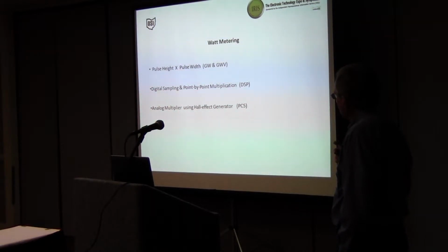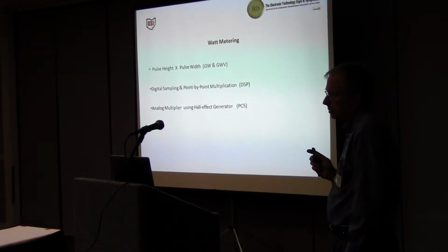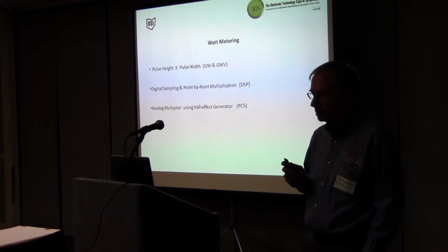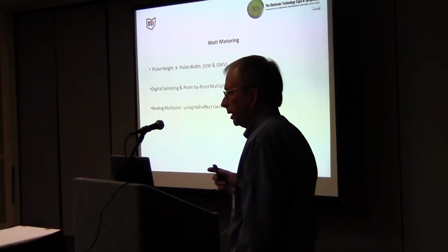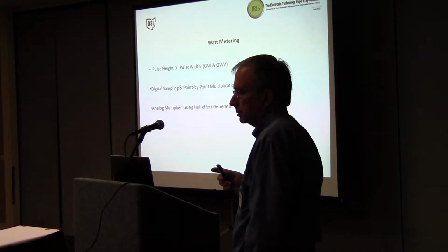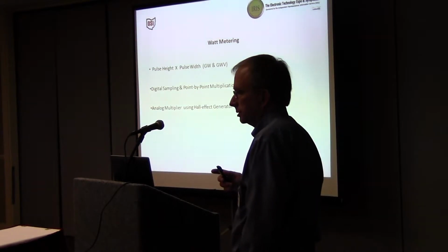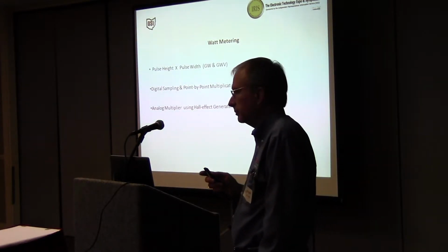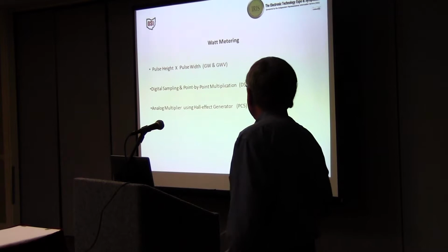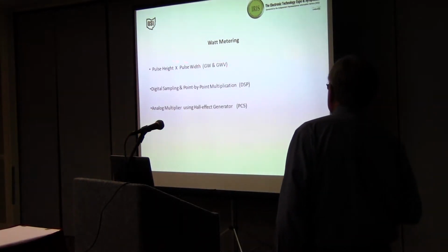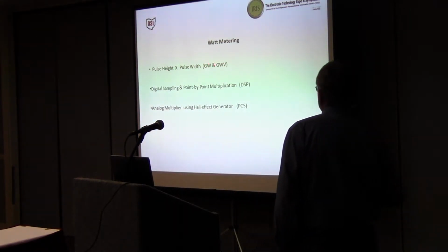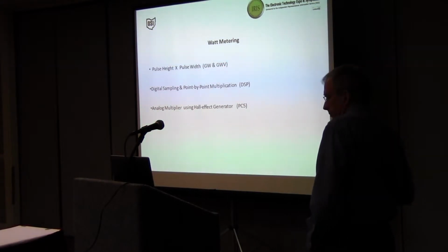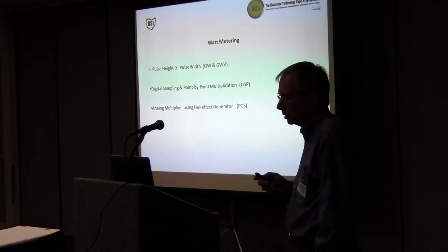We have multiple types of transducers. There's more than one way to measure watts. And if you're using a watt transducer, you need to know something about the style of transducer that you have. We have transducers, and these are our particular model numbers that I'll refer to later, that use what's called pulse height, pulse width modulation.